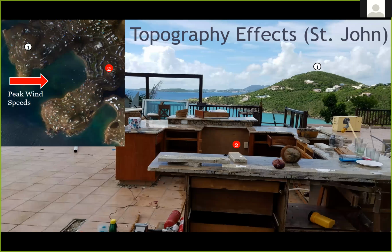In this area we estimate about 120 to 130 mile an hour wind speeds. You can see the hill and the escarpment here, and there should be some enhanced damage effects that we would see because of the wind speed-up over the terrain. But we haven't had a lot of data sets to work with on that, so we've spent quite a bit of time in St. John as well as in St. Thomas looking at that.